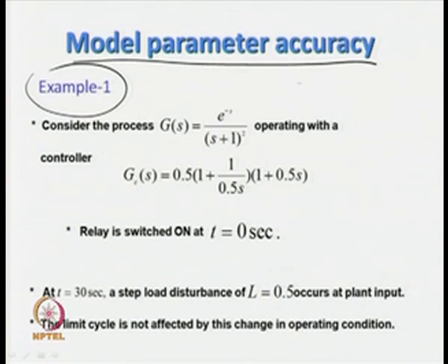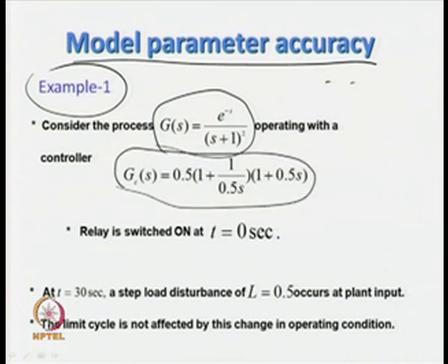That means now we have K equal to 1, or the steady state gain of the process or plant is 1, and I am going to estimate the transfer function model for this dynamics. Since we are going for an online identification scheme, the PID series form of PID controller is used, where it has the general expression K_c times (1 + 1/(T_I s)) times (1 + T_d s).